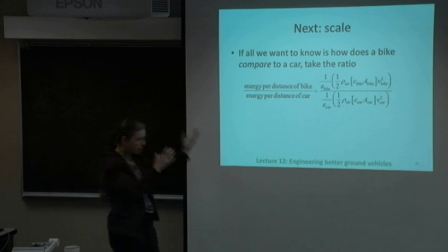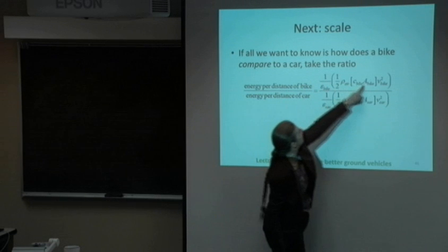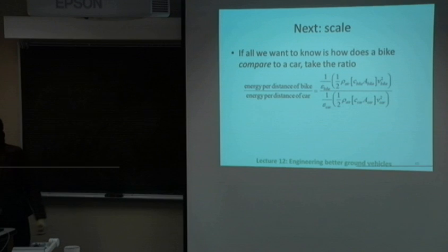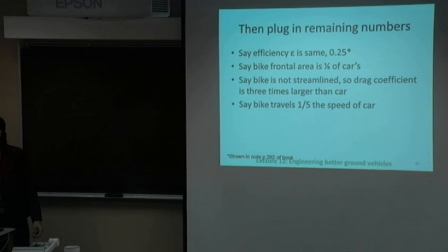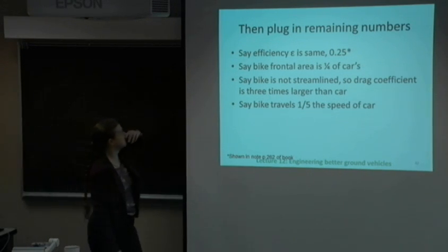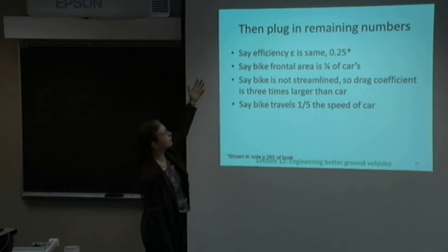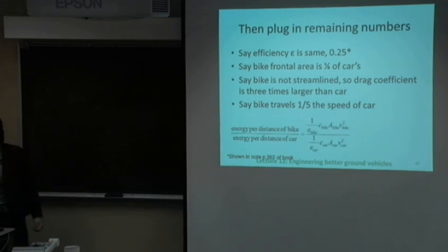So let's say I want to compare the bike to the car. So I take the energy per distance of the bike. Here's that equation, energy per distance. Here it is again. And I see that they both have the half, so I can cancel those. The density of air is the same for both of those. And that leaves me with just this stuff. And then I just plug in the numbers. And I say, let's just say the efficiency is the same, 0.25. This comes from the book. Say the frontal area is 1/4 of the car's. Say the bike is not streamlined, so the drag coefficient...